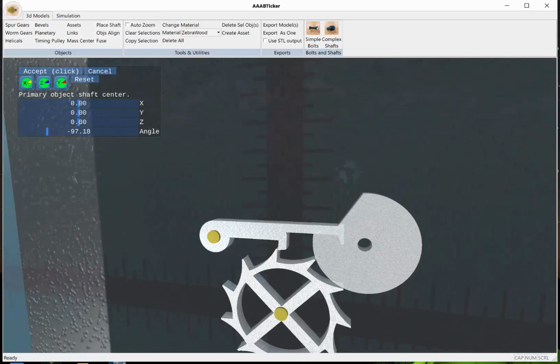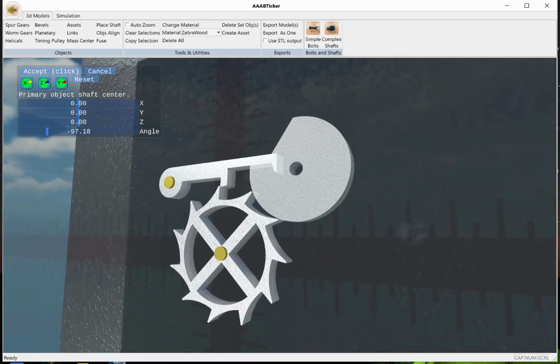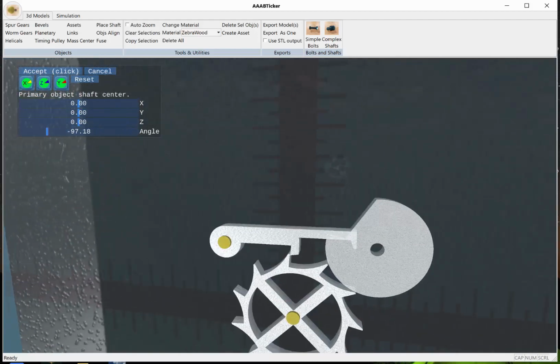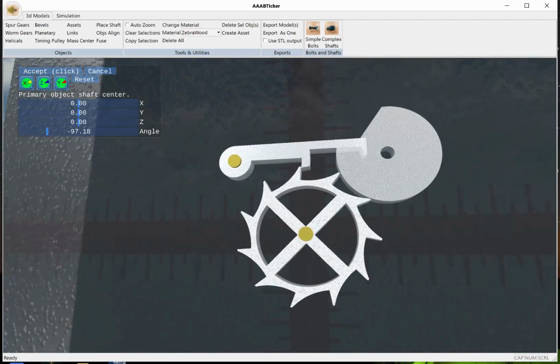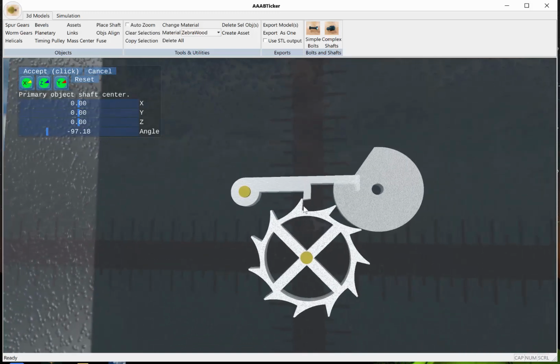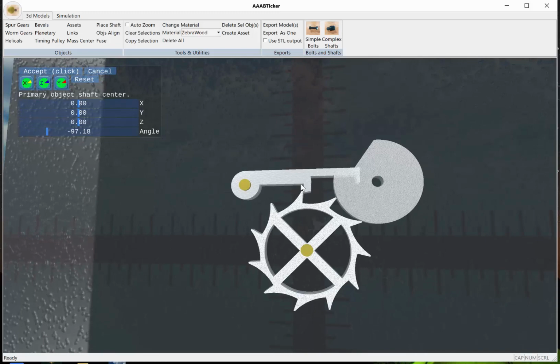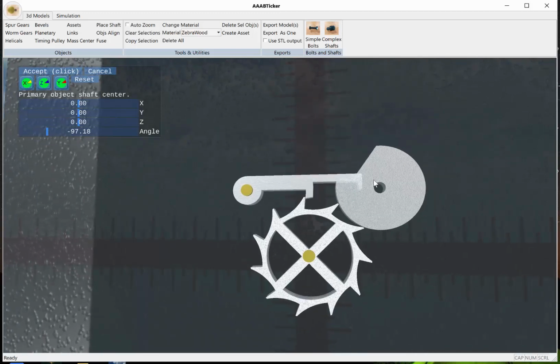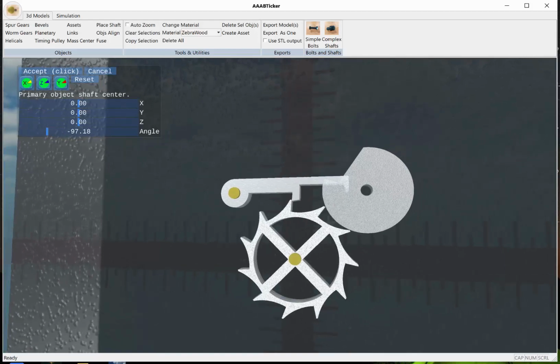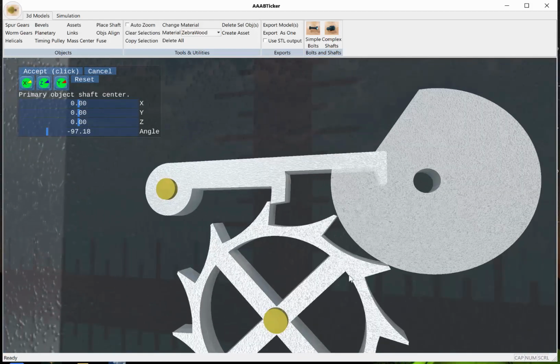Now, you'll notice one other thing here is that this disc is now sitting inside of the trigger arm. And this is because in this type of escapement, the trigger arm actually sits in front of the ratchet. And there's an extender on this section that goes down to hold the tooth. And that's because this disc always has to be in this position close to the points.